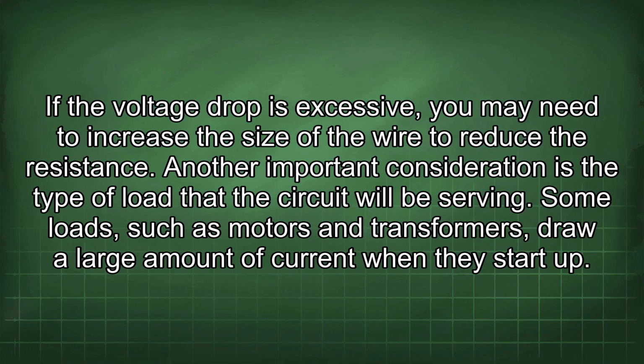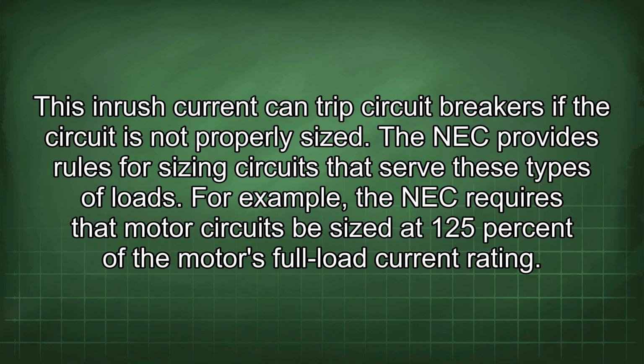Another important consideration is the type of load that the circuit will be serving. Some loads, such as motors and transformers, draw a large amount of current when they start up. This inrush current can trip circuit breakers if the circuit is not properly sized. The NEC provides rules for sizing circuits that serve these types of loads.